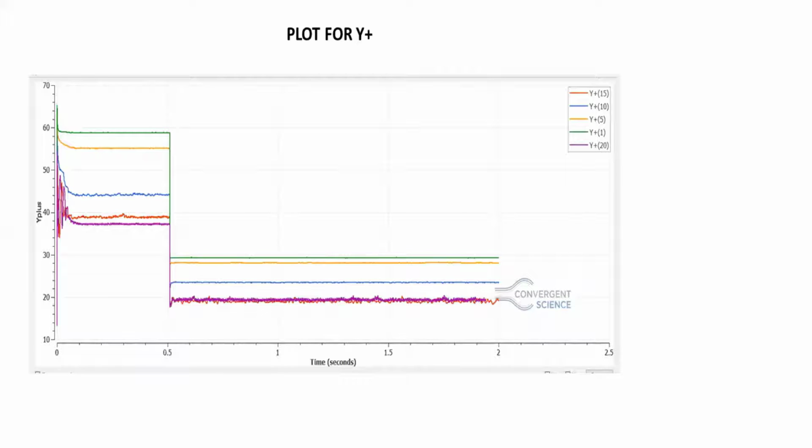So to capture the laminar region also, you need very powerful computers, 120 GB RAM and something like that, or even more. Okay. We are having around 116 GB RAM PC. For that also, we didn't go for Y plus 1. We were able to go till Y plus 30. Okay, then that is also good thing, because that is also going to give you reasonable results.